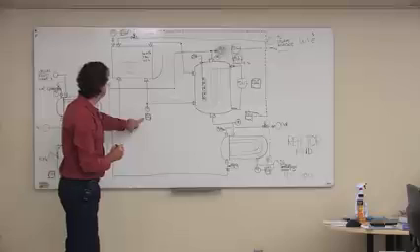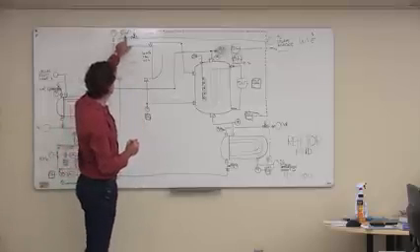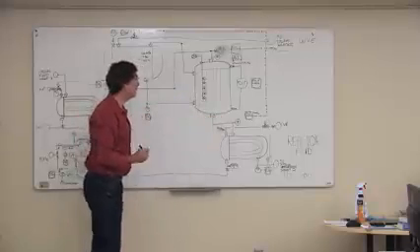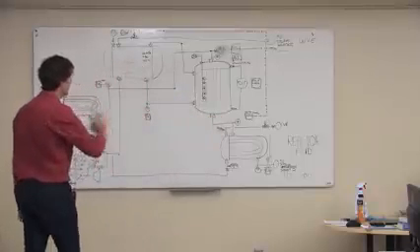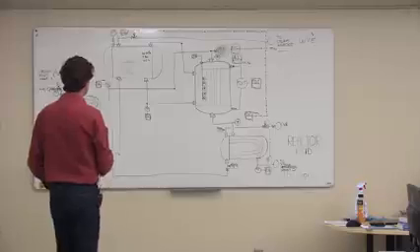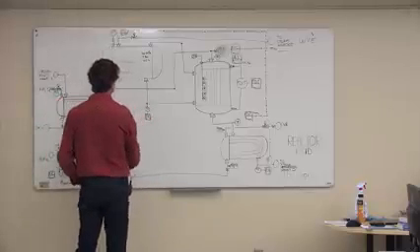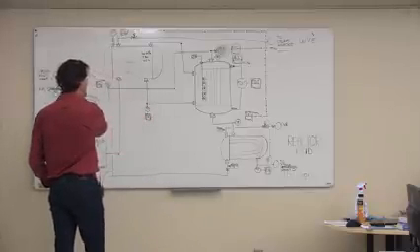No, we don't want to do that. I was going to say we could cascade it into that. We could control the water temperature instead of the process temperature, but it's better just to control the process temperature. It's more direct. So let's just make it an indication so that people can look at it anytime they want.